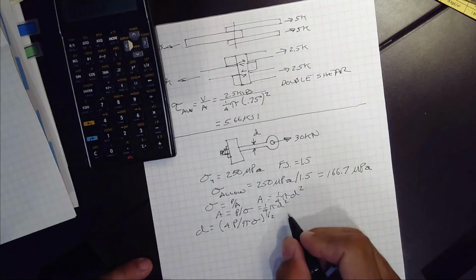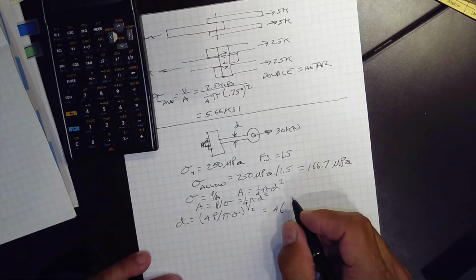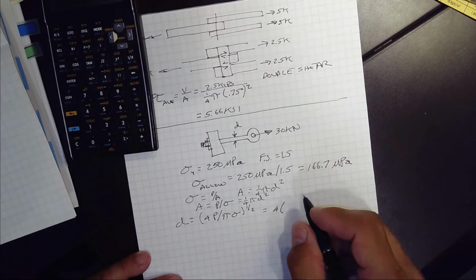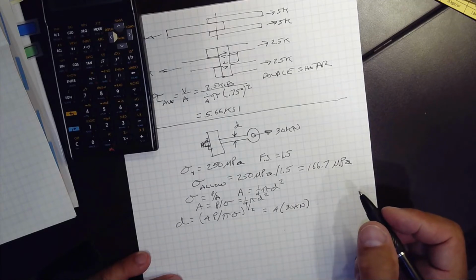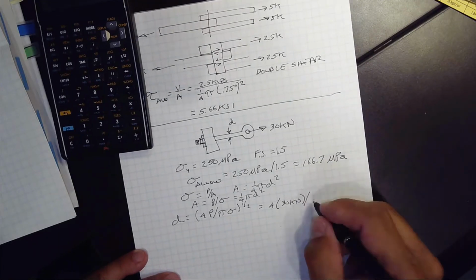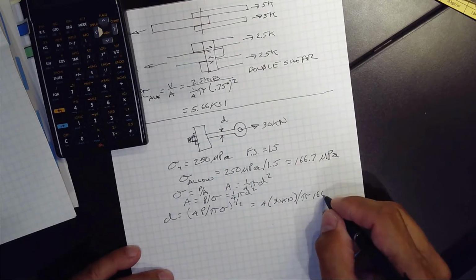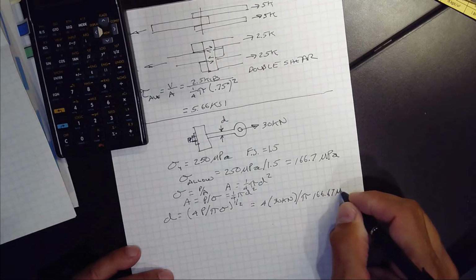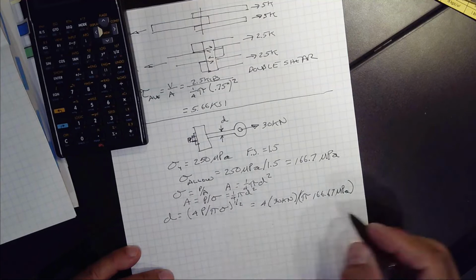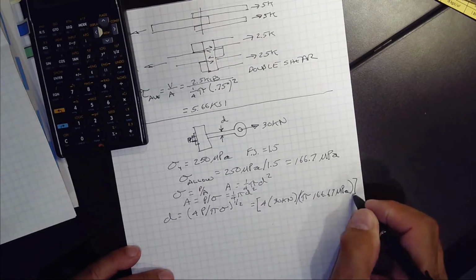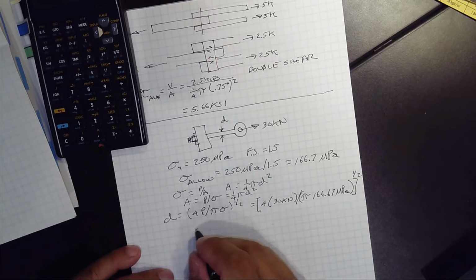All right, so what's that equal to? Let's plug in our numbers. So it's going to be 4 times the load, which is 30 kilonewtons, divided by pi times 166.67 MPa. Okay, so we've got to take the square root of that whole thing. And that comes out to a diameter of